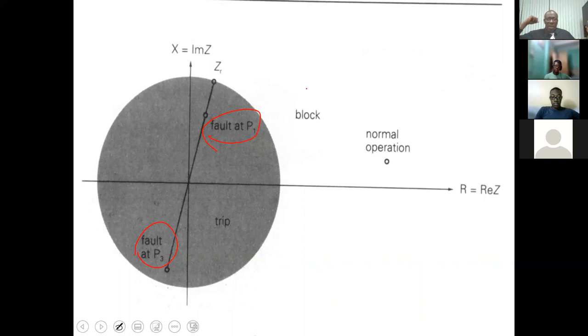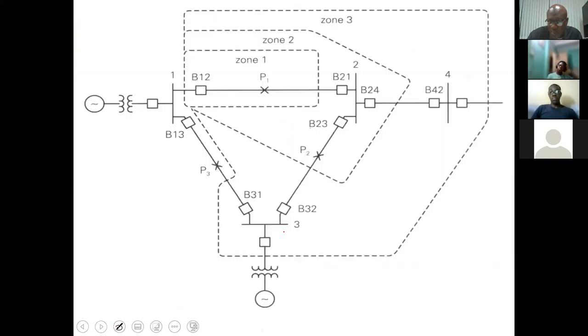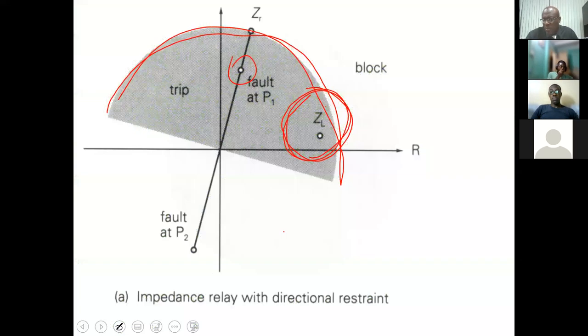And once the impedance is less, West Kings House is then connected to Boulevard. So if the relay is at West Kings House and we are using these characteristics, it will be looking on the line towards Hope and it will be looking towards Boulevard. All right? We say let's put in the directional element so it just looks in front. So let's say we are now at West Kings House and we are looking towards the Boulevard. So that's what we would see.